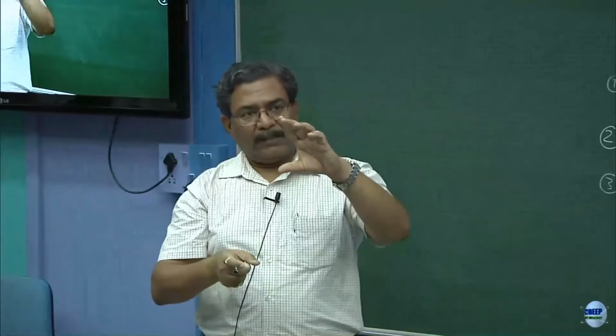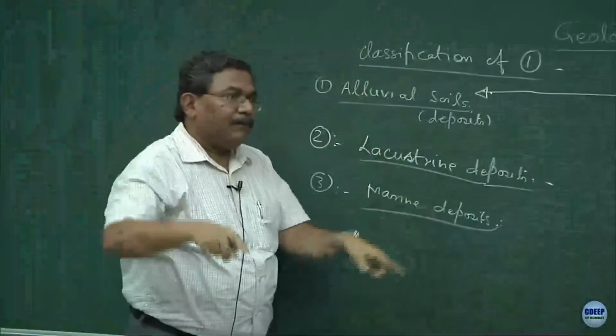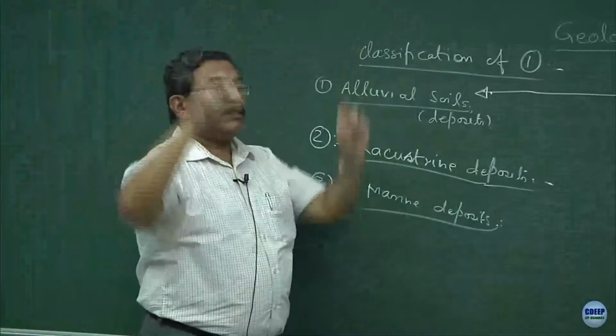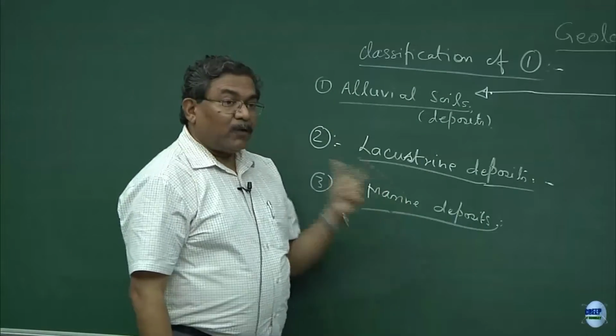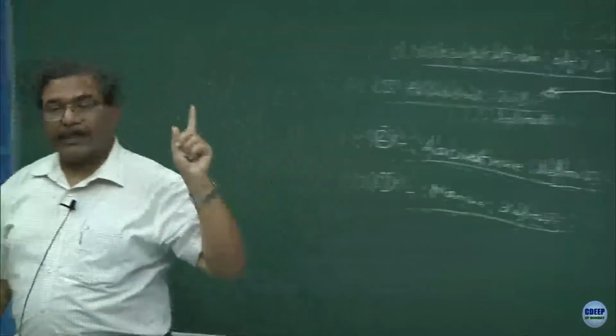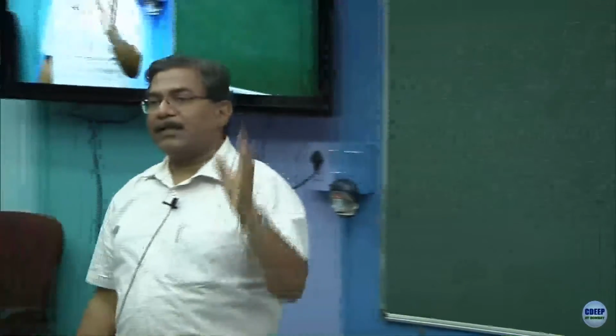This is your triangular portion, we call it the Deccan trap. All along this Deccan trap, the soils which you get in the coastal regions are marine deposits. It could be because of delta formation we were discussing, suspended particles coming, and because of the density contrast of the fluid, they get deposited and formed over there.